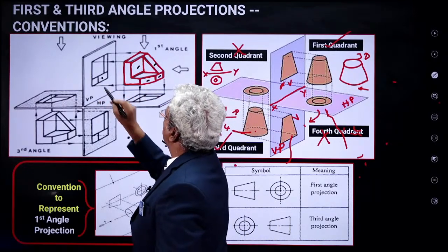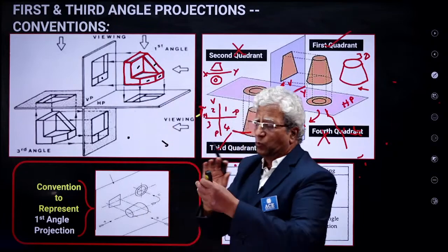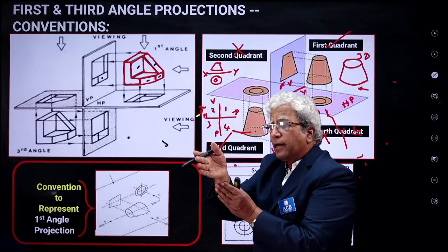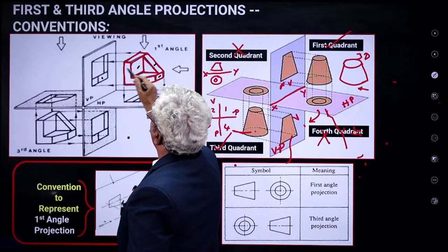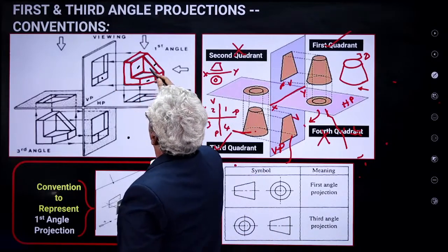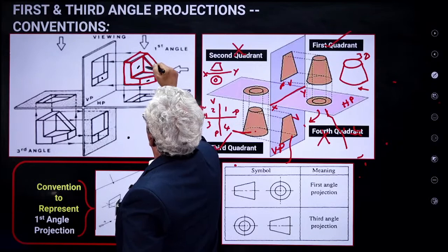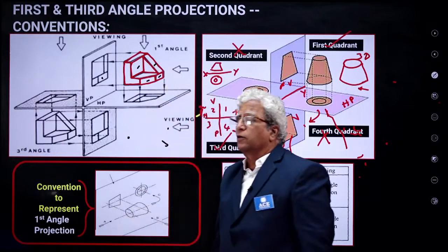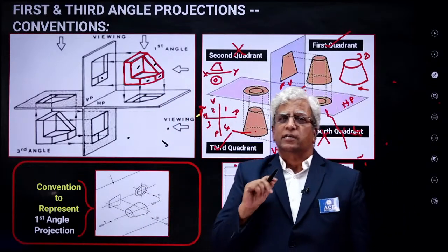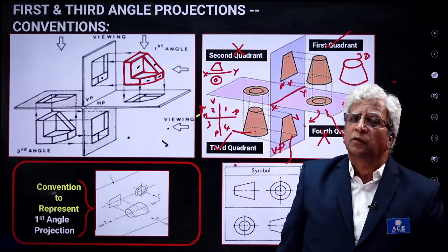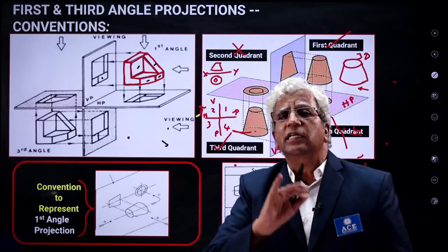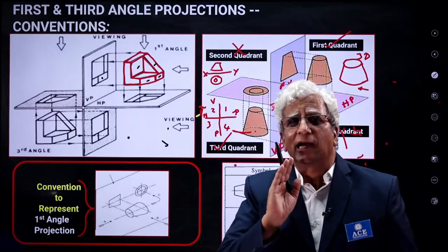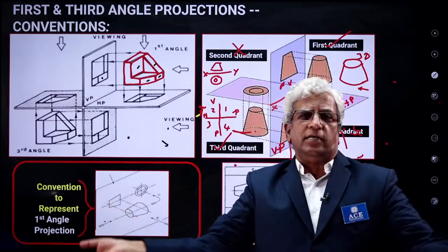This surface is shown here. See, its length is more, but in a slant manner, therefore it appears with less width. Similarly, this appears as a rectangle, and these, because they are parallel to the projectors, we cannot see. So this may be a question: what are the surfaces which you cannot see in a view? Any surface which is parallel to the projector, you cannot see.